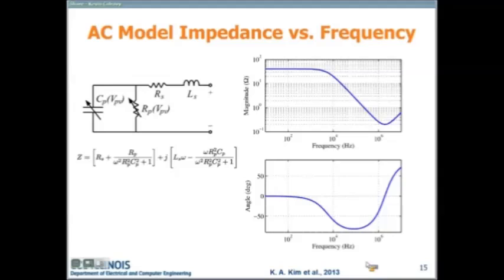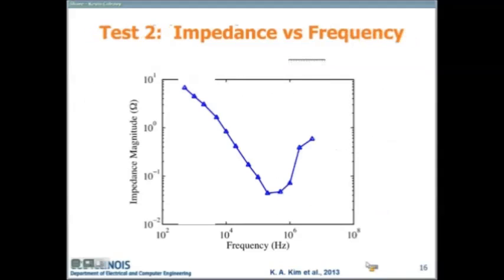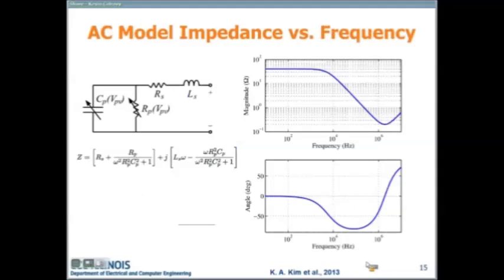So using that knowledge, we can take a sweep at the higher frequency of our cell using the AC test and just try to find those specific parameters. I did it for both, but I'm only showing the polycrystalline cell here. They're actually very similar. And although this isn't perfect, this is in the higher frequency, so this is just this part of the curve, following me.